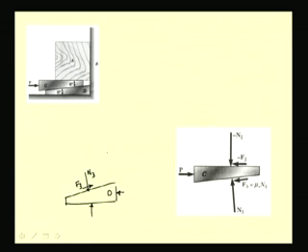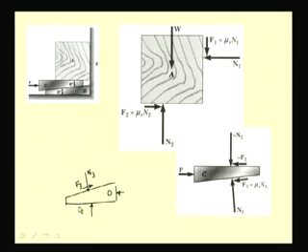Now, we can consider the free body diagram of the block. So, on the block face this force F2 is equal and opposite to the same. So, it is marked in this direction. We have the normal reaction and the weight of the block, and since this block is tending to rise against this vertical wall, we have this frictional force opposing the motion.